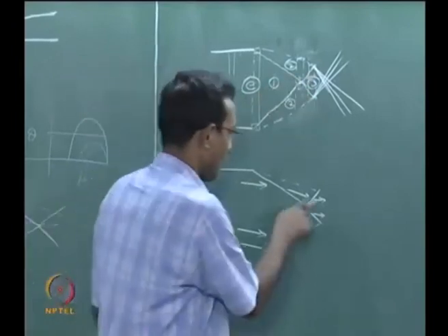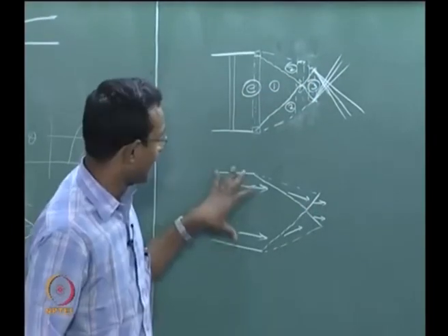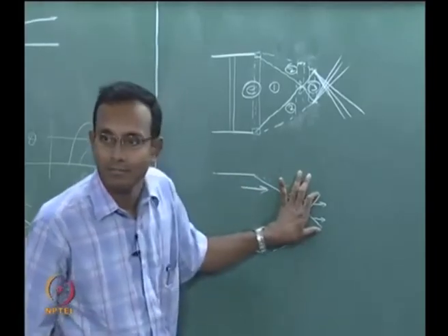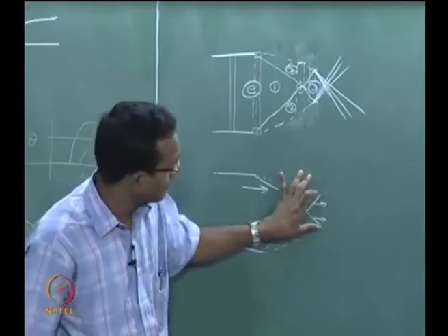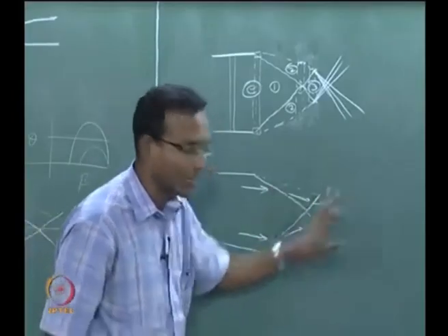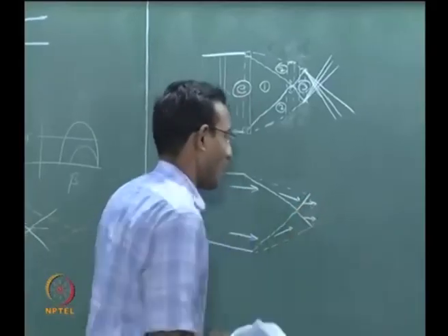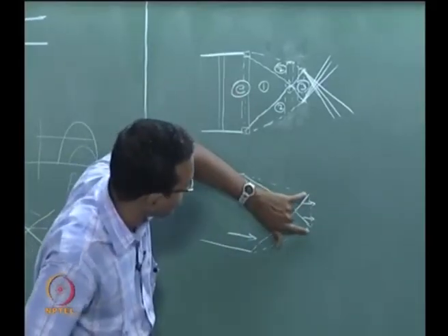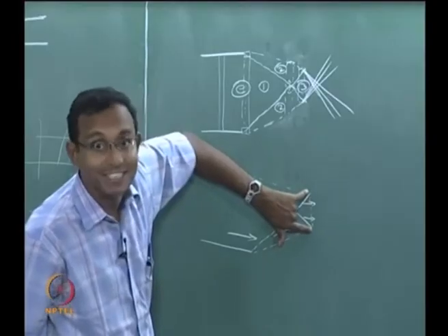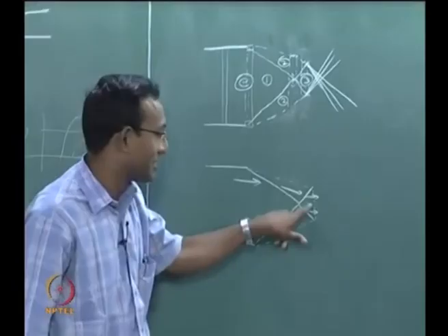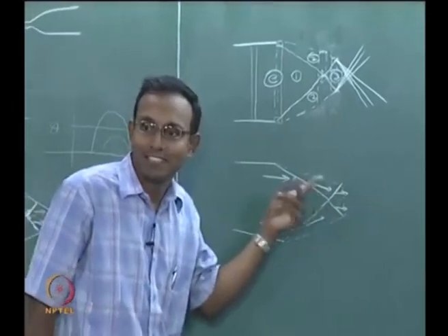Flow velocities are parallel. It is as if this jet has been shrunk to a smaller size jet here. I have come up to that point. The jet has become a smaller size jet and they are going parallel out like this. And when the jet comes out of this point, the very first point when the jet-like thing comes out, immediately it is seeing that pressure outside is lower than the pressure inside. That is another way of looking at the same thing.